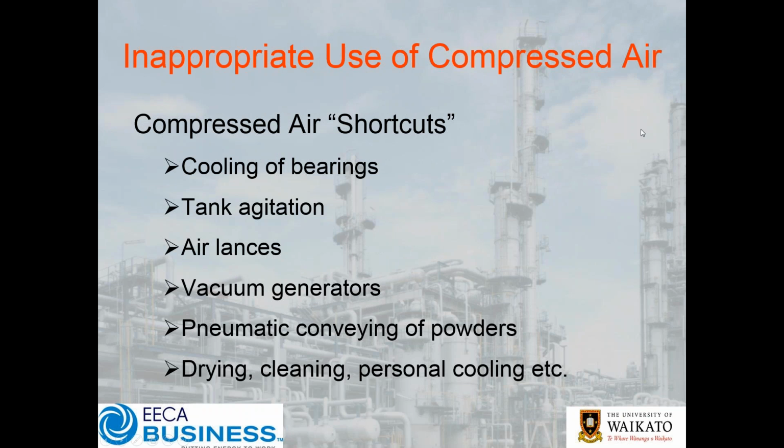So let's move on to inappropriate uses of compressed air. These are what I like to refer to as compressed air shortcuts. So we're talking about where we're cooling bearings down with compressed air, agitating tanks, air lancers for blowing material around, vacuum generators, pneumatic conveying, as we've already mentioned, drying, cleaning, personal cooling is an all-time favourite of mine.